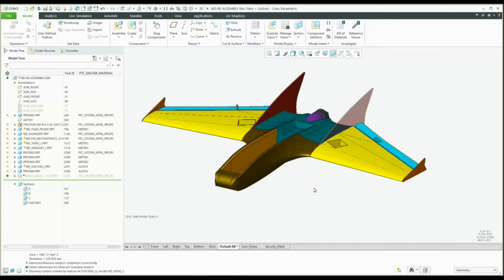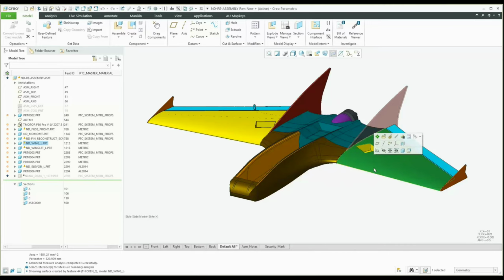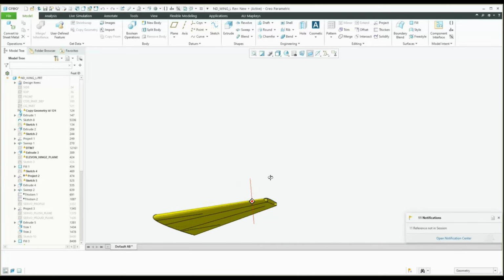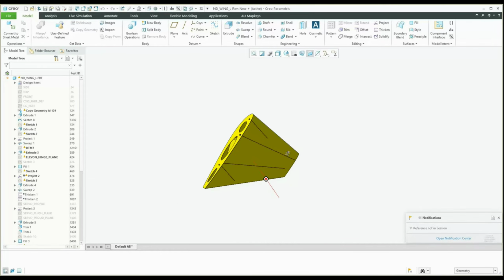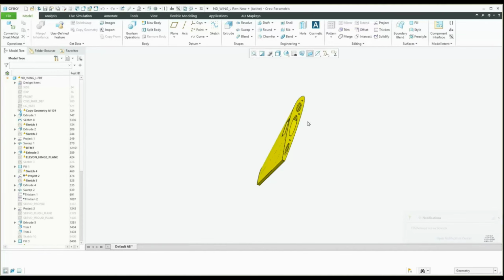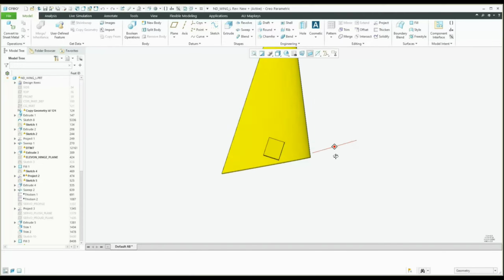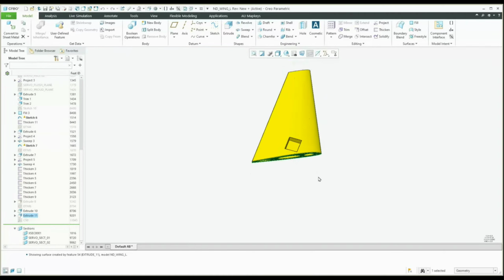Let's take a look at how I incorporated spiral vase printing into the design of the Tiny Drak parts. This is the left wing. I modeled it by assembling it with the unibody I had previously modeled, and then importing all surfaces relevant to the individual wing part I was designing. I then added detailed features to set up the specific structures that I would be printing.